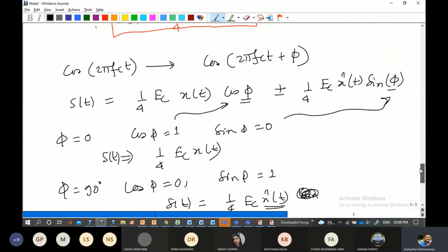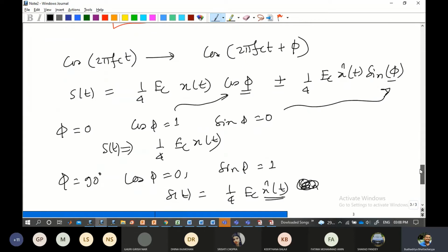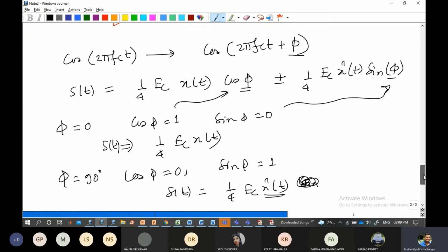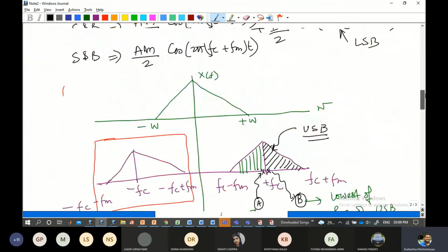And also here you can observe, as we all know, that for the same purpose in DSB-SC we discussed the same thing, that when we are doing coherent detection, there is always a problem that a phase shift will be there, and that's why phi came in as per our discussion, where phi is the phase difference between the tuned local carrier and the transmitted carrier. So that again came up to an idea that there will be a non-uniformity taking place while we are taking into account this particular method. So this was a basic wrap up of what we had discussed in last day's class.